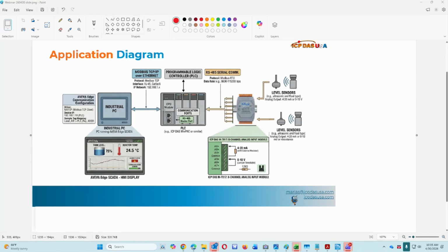The key to this is this connection right here, which is done over Modbus TCP. In this diagram, the PLC communicates as a Modbus TCP server or slave, and the industrial PC could be anywhere within the plant, local, or in outer space almost, connected just by Ethernet through a system of standard networking, like through routers or switches.